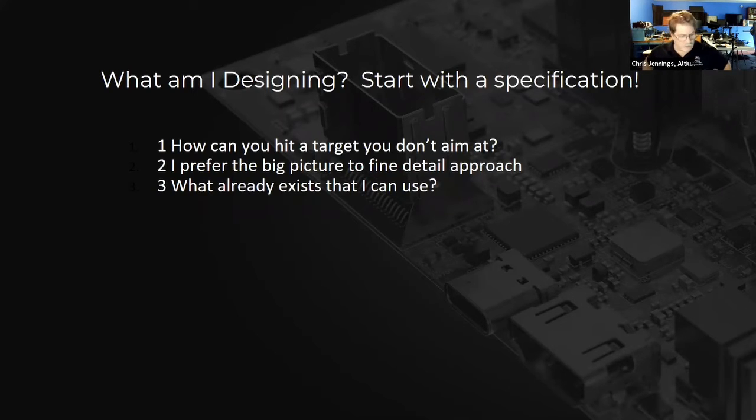Altium has a concept called design reuse. And so we typically allow you to take an existing schematic. In this case, I'll show you an example of the power supply that I used. That power supply schematic was used for multiple opportunities for a couple of different jobs along the way. The advantage, again, I knew it worked. I knew the parts were available. And I'd already done a layout a couple times with it, so it was a lot faster to get the layout finished because I had some template and guides for that layout. Again, it's critical.